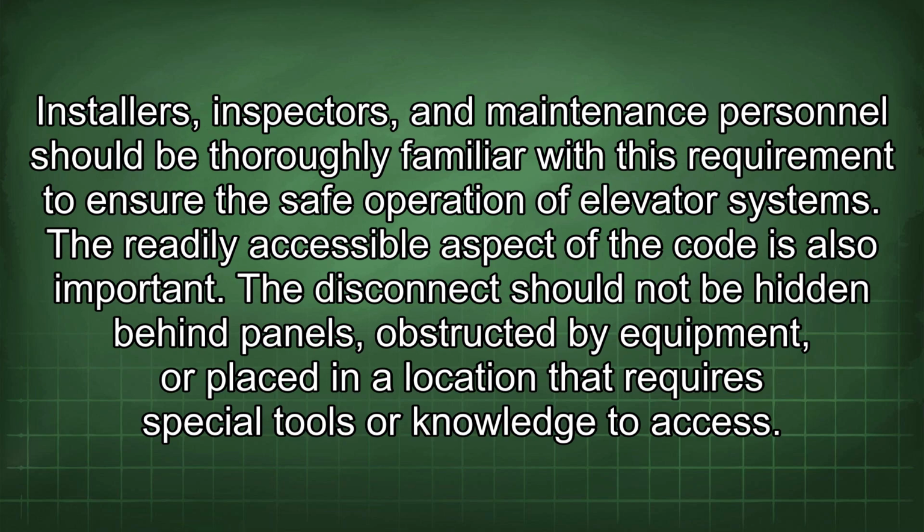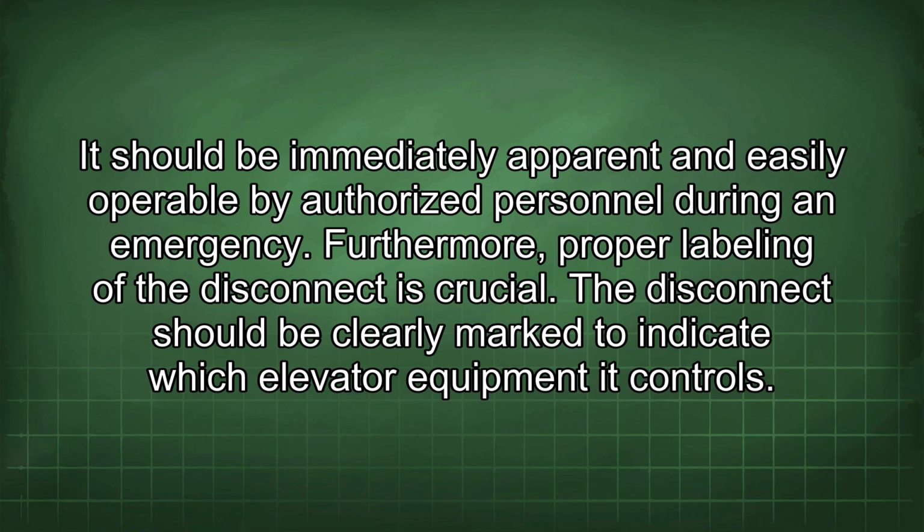The readily accessible aspect of the code is also important. The disconnect should not be hidden behind panels, obstructed by equipment, or placed in a location that requires special tools or knowledge to access. It should be immediately apparent and easily operable by authorized personnel during an emergency.